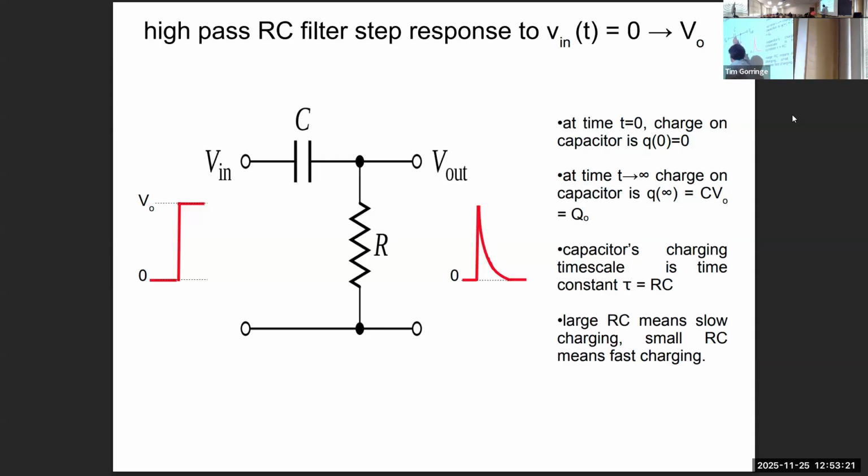So it's the same arrangement of a series capacitor and resistor, but now the input is across the series arrangement again, but the output is across the resistor in this case. So in this case, if we put in a step function again on the left-hand side, we get out this impulse with a time constant on the right-hand side.